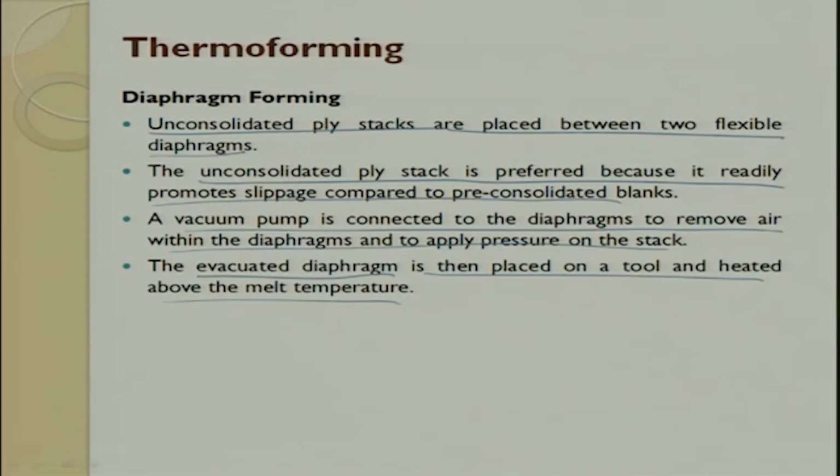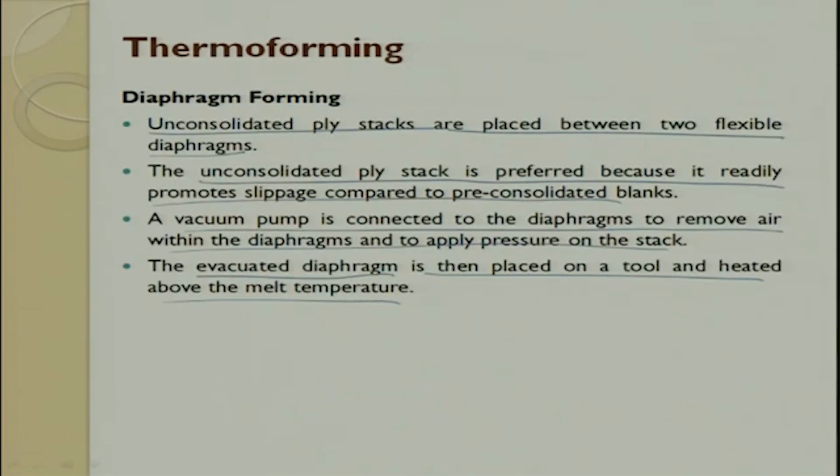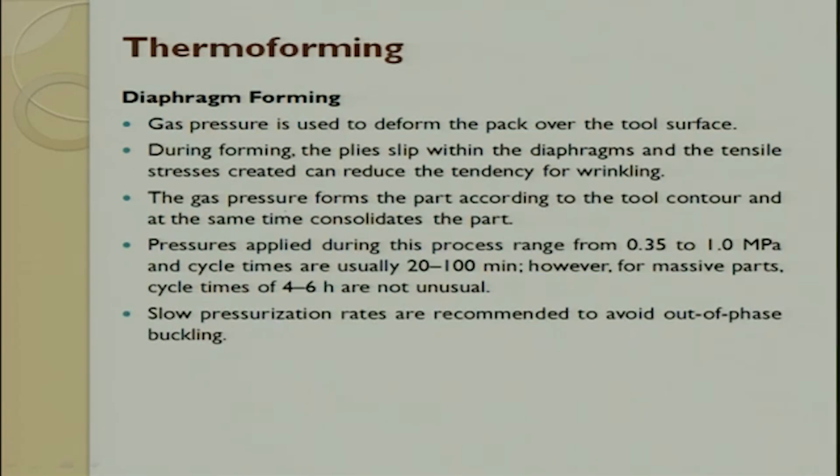Unconsolidated ply stacks are placed between two flexible diaphragms. So, you can see the diaphragm here. The unconsolidated ply stack is preferred because it readily promotes slippage compared to pre-consolidated blanks. So, this is very important so that you get a sound quality output.